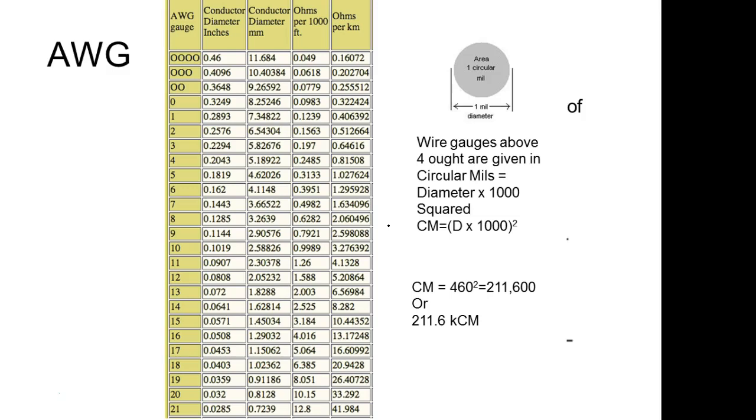Well, we actually use three, depending on whether you've got some real high current stuff. We use a lot of 14 gauge. And this is the size of the conductor. This is the ohms per 1,000 feet. So 14 gauge wire is 2.525 ohms per 1,000 feet.